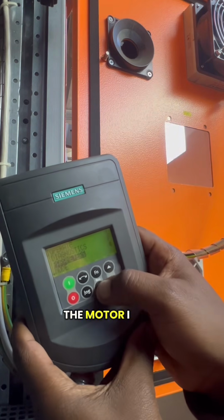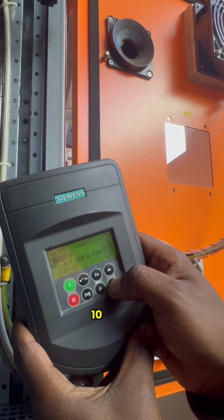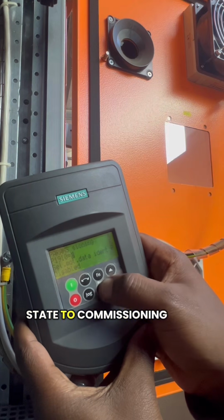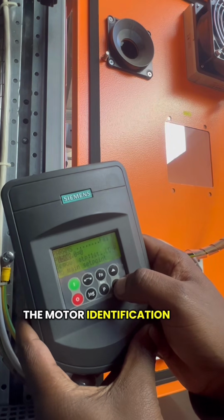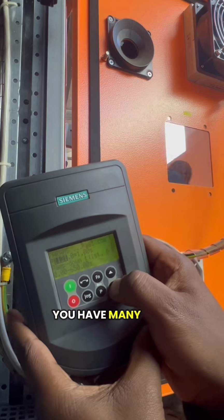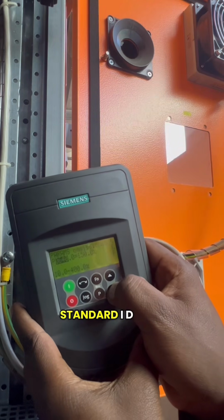Now, coming to the motor ID run, there are just three important parameters. The first parameter is parameter P10. P10 is to switch your drive from ready state to commissioning state. Then the second parameter is the actual parameter for the motor identification. It's parameter 1910. You have many options. By default, it will be on 0, but you're going to put it on 1 for a standard ID run.